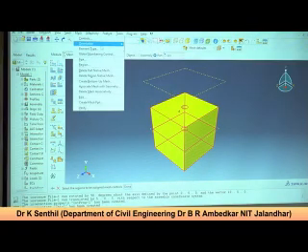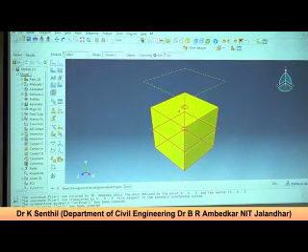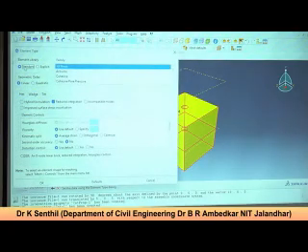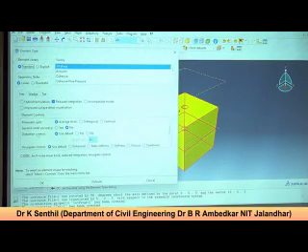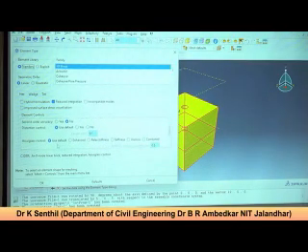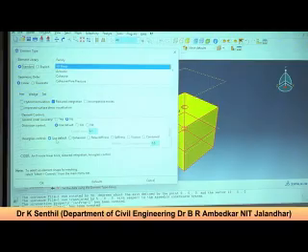Now you can go to the element type. Here you can see the standard or explicit analysis. You can select whatever you like. Then here you can find distortion control, hourglass control. See, this is a very important thing. Hourglass control is very important, especially when the internal angle of the mesh is less than 60. Also, if the internal angle is more than 135, it creates problems.